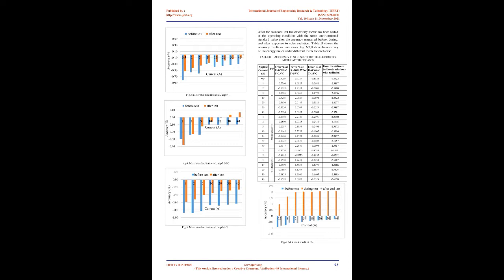The solar power meter, a pyranometer, model trademark 207, used to measure the output radiation of the lamps, is connected to an external sensor via a wire with a length equal to 1.5 m. The pyranometer measures irradiance from 0 to 2000 W/m2 with plus or minus 5% accuracy. The climatic chamber that is used can control the environmental conditions from minus 40 degrees Celsius to 180 degrees Celsius and humidity from 45% to 95% RH.